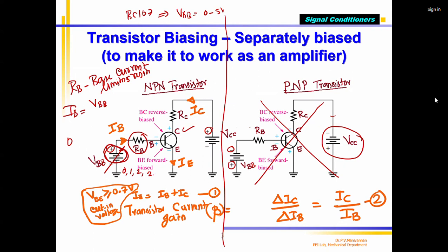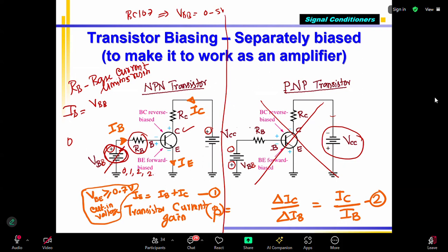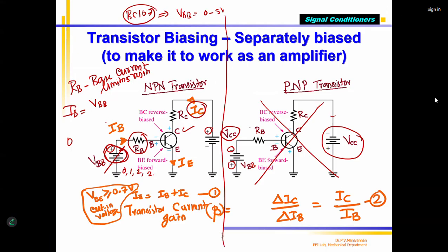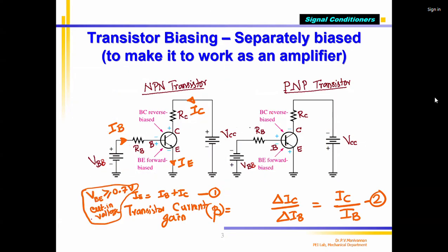That is maximum. So when I want to buy a transistor, you have to see the data sheet. You have to see what the voltage levels are. VBB, what is the maximum voltage? VCC, what is the maximum voltage? What is IC max? What is IB max and beta? Important parameters for a transistor, note down, are VCC max, VBB max, IC max, then IB max, and lastly, beta.